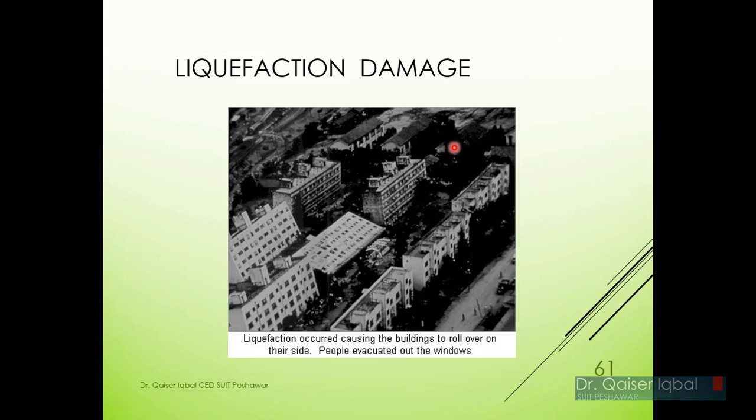Here you can see another important phenomenon in granular soil, which is called liquefaction. If you have a granular soil like sand, and if it is fine sand and not compacted, and if it is fully saturated as well, and it is hit by an earthquake, by a seismic force, it can liquefy.